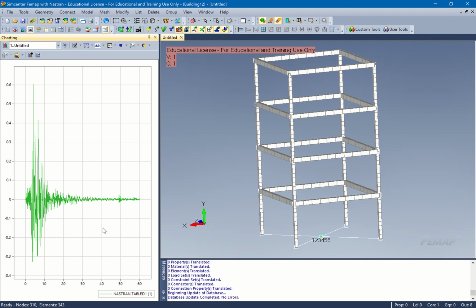The magnitude. The bottom line is no. Is there like a local magnitude? Looking at this side of the graph, you can tell how hard it was shaking at that location, yeah. But you can't relate that to the earthquake magnitude. Right, so how does that translate from like 0.6? 0.6 Gs. Okay. Everything's normalized into Gs, because no matter where you go in the world, metric or English, everybody knows what a G is. So basically, this is half a G. Half a G acceleration is a lot for a building to take.